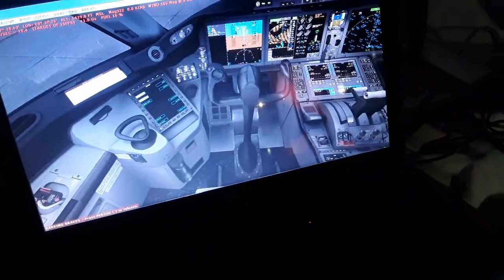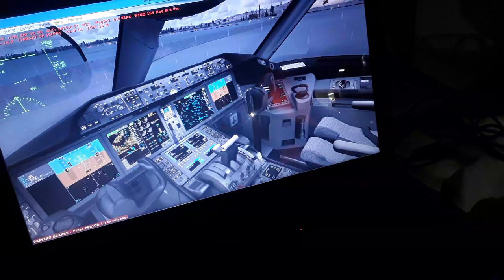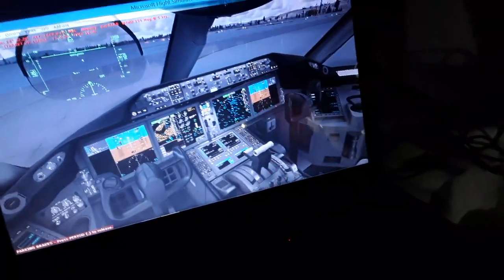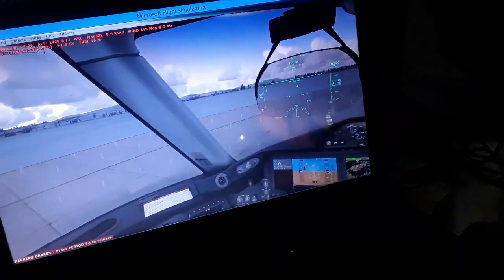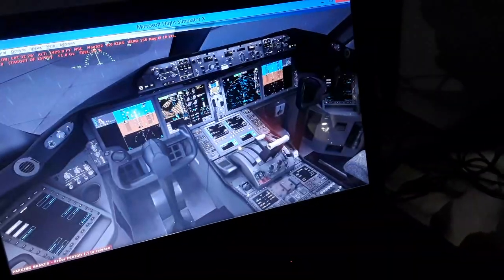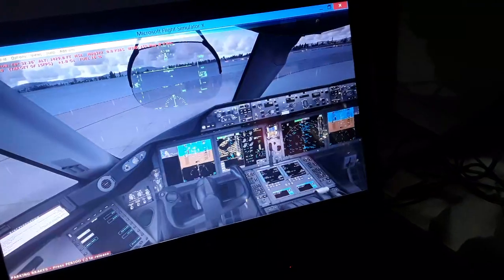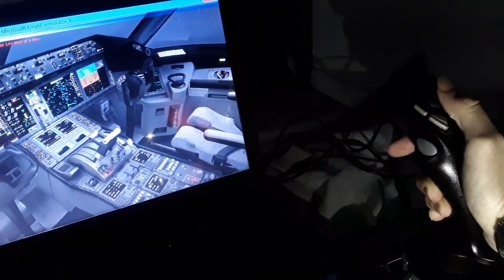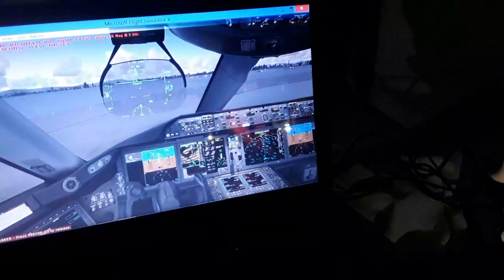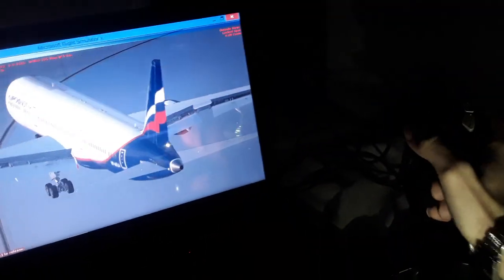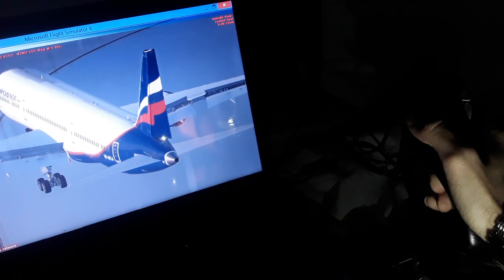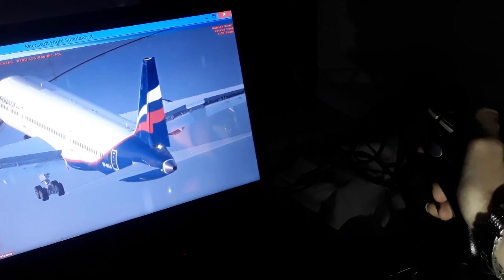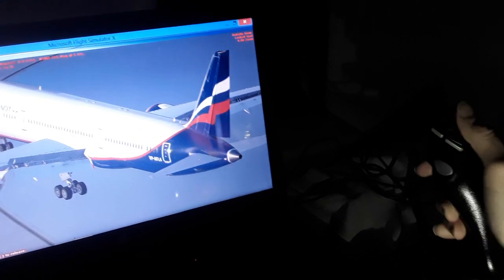Also in the rudder pedals we have the nose wheel steering, the tiller interconnected, and ground speed scheduling, like from 0 up to 45 knots. It's decreasing from 76 degrees to 7 degrees. Then from 45 knots, like 70 knots, it decreases to 0 in takeoff. And then we have only the rudder aerodynamically effective above 45 knots and for takeoff. So you use only the rudder after that speed in takeoff. Maybe like 70-80 knots after, it's only rudder, no nose wheel.